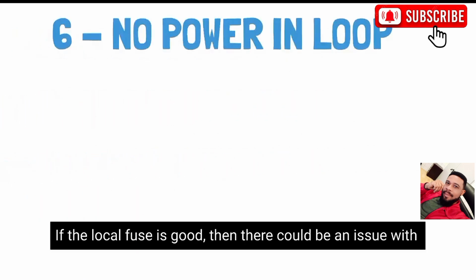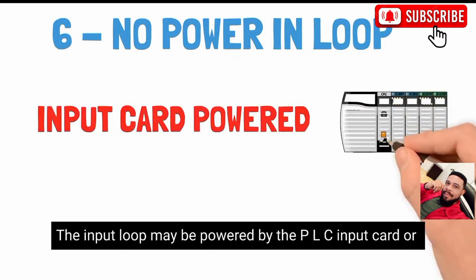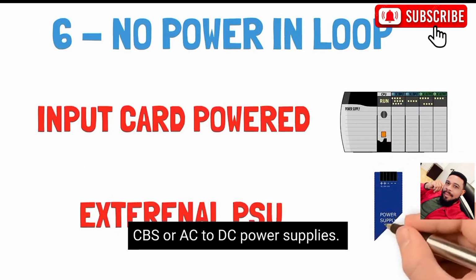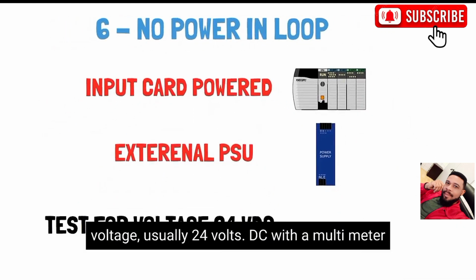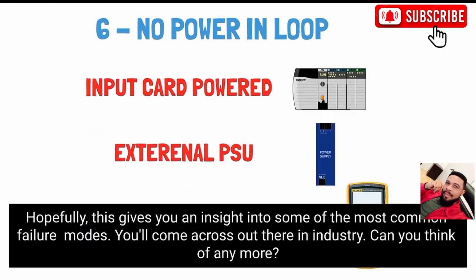No power in the loop. If the local fuse is good, then there could be an issue with power upstream of the local fuse. The input loop may be powered by the PLC input card or some external 24-volt distribution via local MCBs or an AC to DC power supply. The power for the loop may have been lost. Check the loop for a suitable voltage, usually 24-volt DC, with a multimeter. Check for a tripped MCB or power supply status LED.